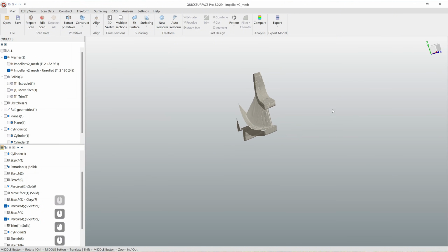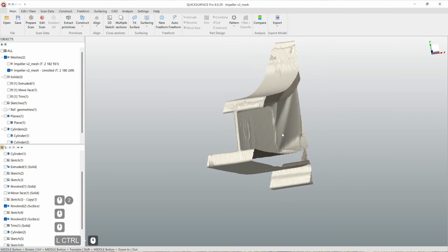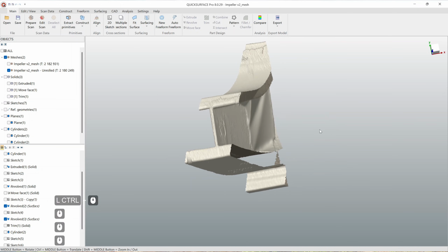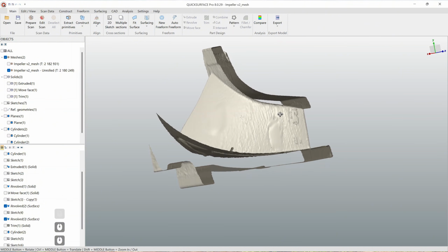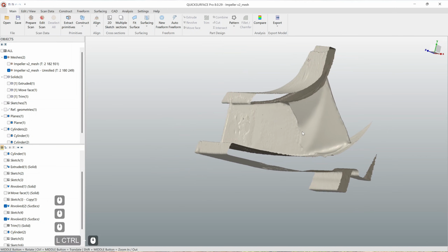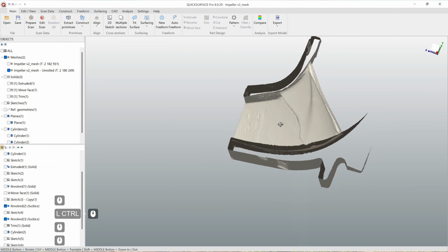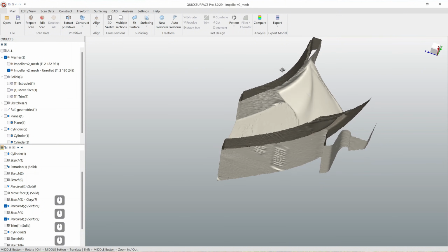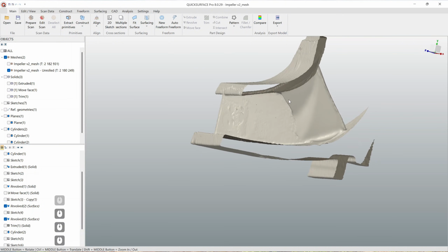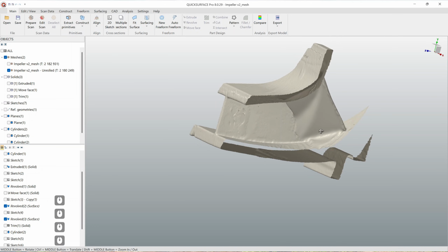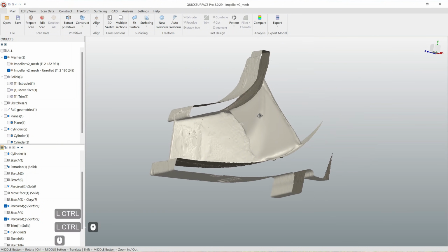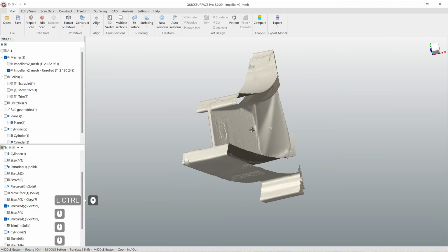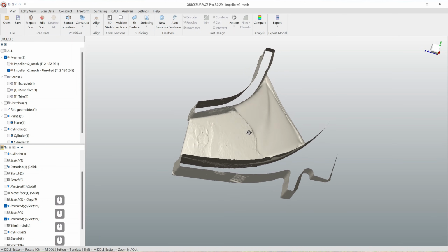Okay, looks good. So here we can see that from one side this blade is scanned pretty okay. We have most of the geometry. And on this side it's not that perfect, so it wasn't scanned completely here and all across this region, and later it got filled in your scanning software. Well, in most cases when I am scanning something, I'm disabling this option to fill holes.